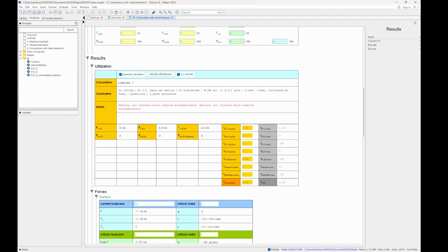This is for the active part, and this is for the most critical load case of each of these parts. So we have a check for code 8.1.2, a check according to Eurocode 8.3.2, 8.1.4, 8.3.3. We have the net section active, we have Annex A, and we have the bolt steel, and we have the worst of these utilization factors listed here. Red is bad.